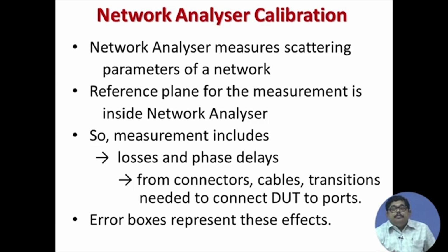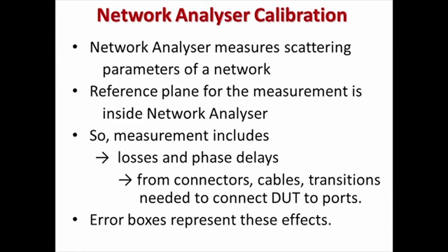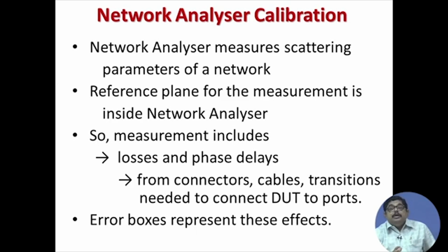Now, in network analyzer, when we discuss its architecture, we have seen that the measurement of scattering parameter is reference plane dependent. If you change the reference plane, the S parameter gets changed. Now, in the network analyzer, its reference plane is quite inside the instrument.